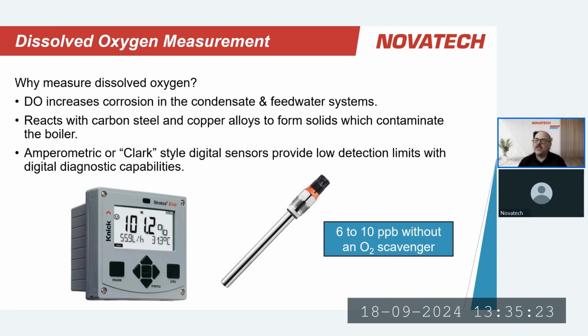So imagine we're using steam in a heat exchanger in a refinery or a petrochemical plant. The risk of contamination now, or what we might see if there's a leak in a heat exchanger tube, would be things like hydrocarbons breaking through.